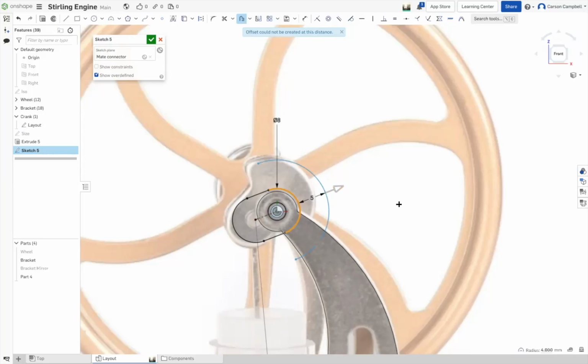I don't know how to accept this stuff. 4, 3. You can't do that. So yeah, there you go. Let's try that for now. Say okay. The arc that has 8 millimeters defined, change that to construction. Nope. Pick the arc, not that one, hit Q.